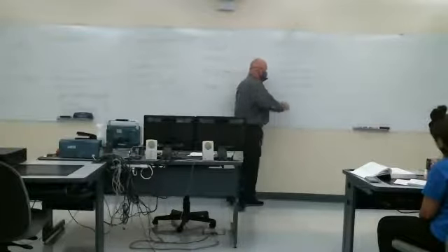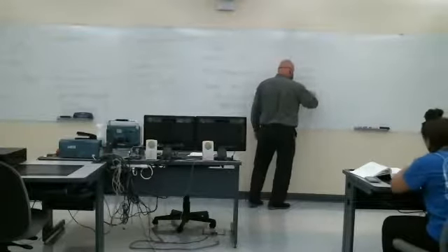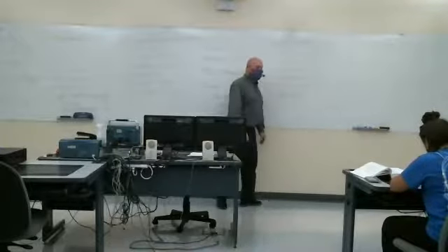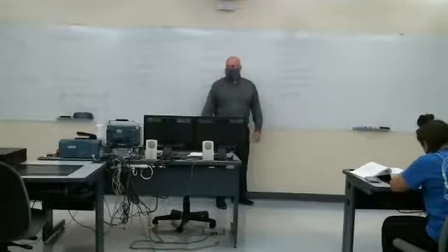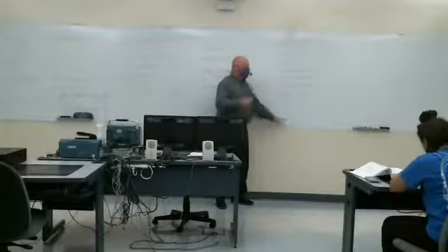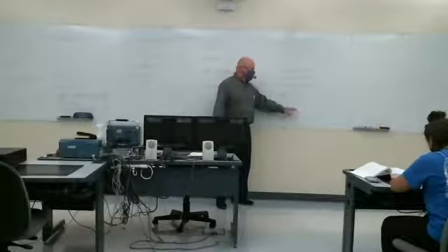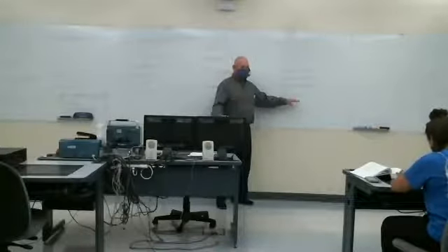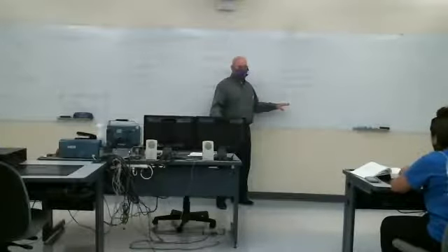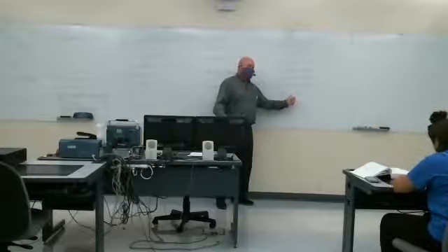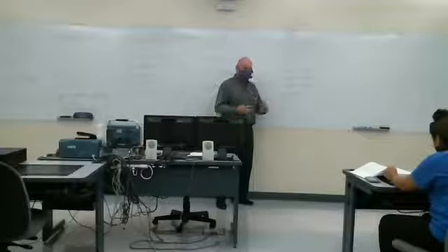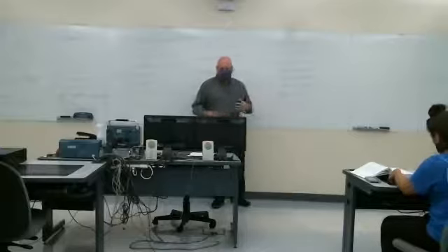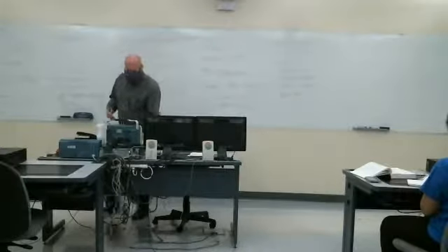Again, let's take the case, make things simple. Let B and C both be 1. Let X be 1, the output's 2, right? If I double the input, so that X is now 2, what's the output? 3. Well, what if I doubled the original output, which was 2? I get 4. Again, they're not equal because of this offset. Again, without that, it is a linear system. So it's not always intuitive.